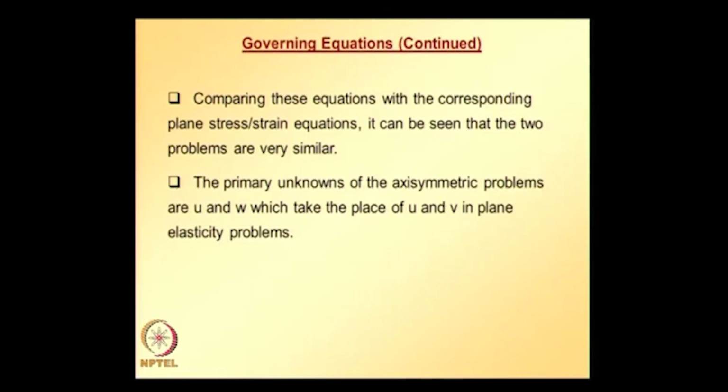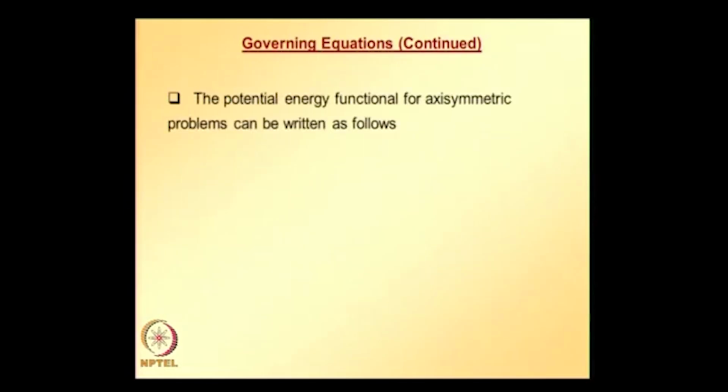So, before we derived finite element equations for the axisymmetric linear triangular element in the last class, we also looked at the potential energy functional. The potential energy functional can be written similar to what we have written for plane stress plane strain problems, because both problems look similar except the displacement components are different.